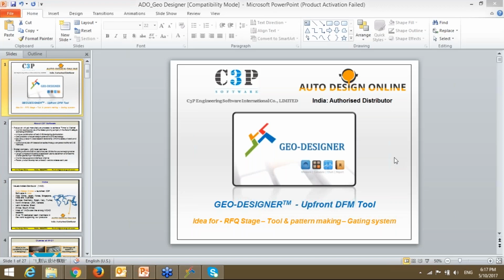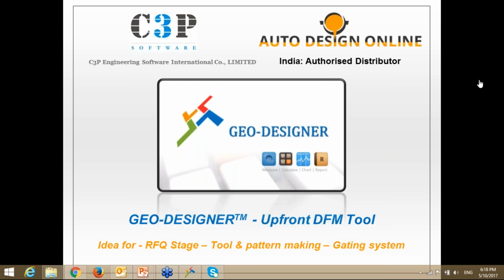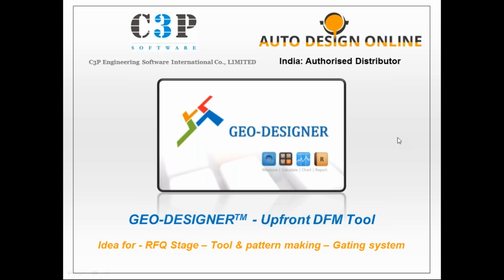Okay, so today will be the webinar of our first session, where the topic will be how an upfront design for manufacturing tool could be used by the foundryman or by the OEM to understand in the shortest possible time about the casting part geometry and where we have the higher masses which are likely to get hotspot or shrinkage later on.